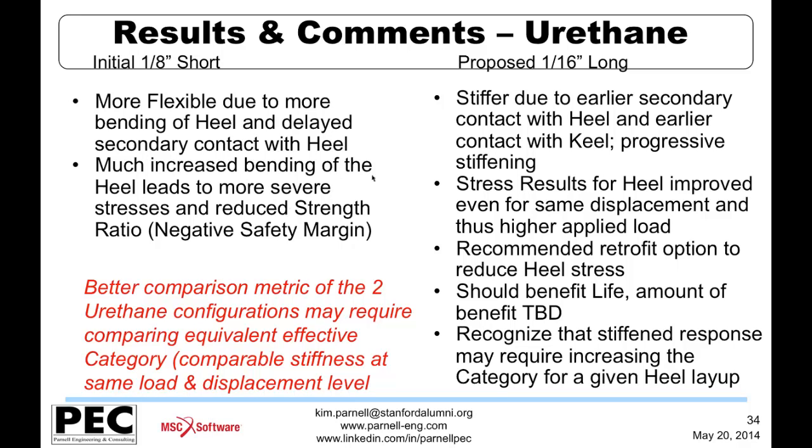So we'll talk a little bit more about that in a moment. This other urethane pad provides more secondary contact or earlier contact. You get a lot more progressive stiffening out of it, and it looks like it has some definite benefits in terms of providing additional stiffness, but with less overall bending response.